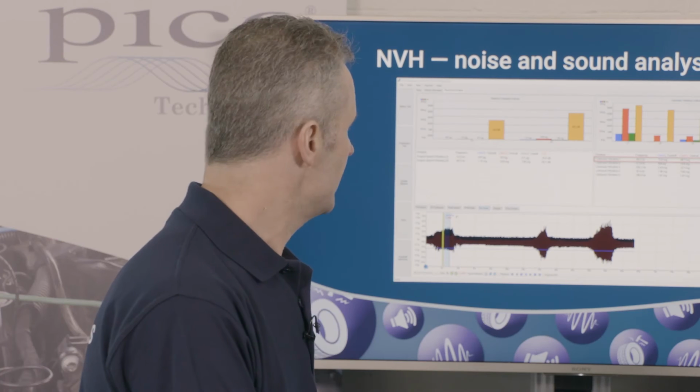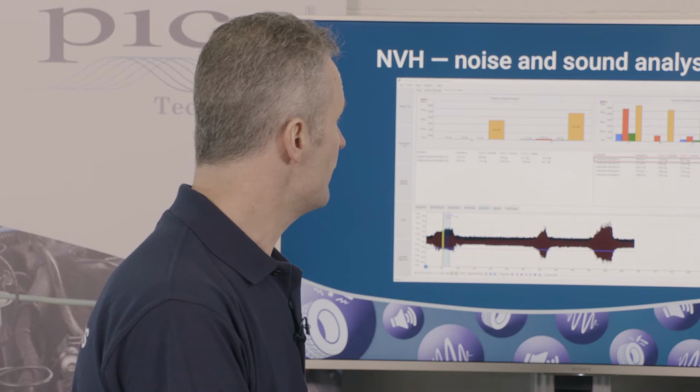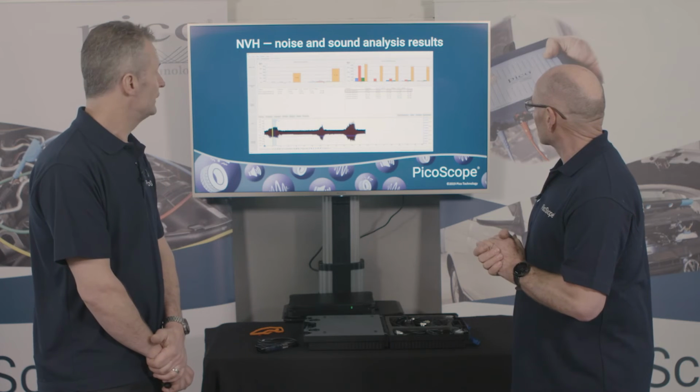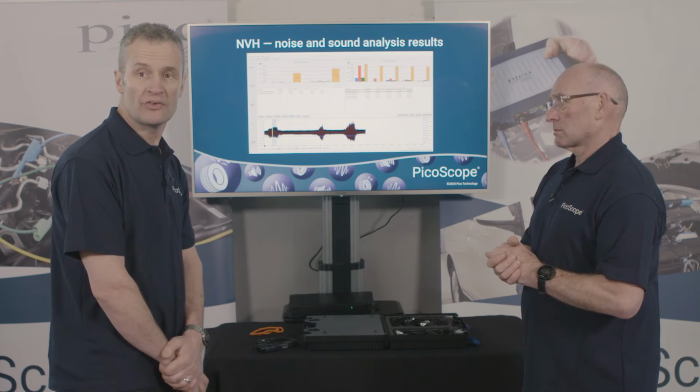So we had concentrated on the frequency view. This is exactly the same data, no different, but in bar graph view, where we've used the software to highlight the known vibrations on the left and the top 5 unknown on the right. In this scenario we had 39 Hertz. Remember, cooling fan frequency would be dependent on battery voltage as well. So if we are going to run the cooling fan for simulation, battery voltage is key for RPM.